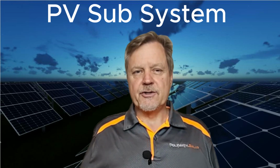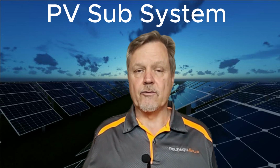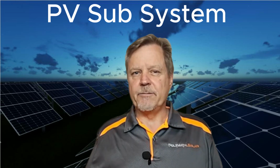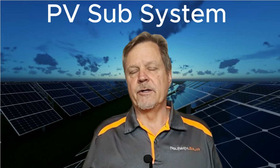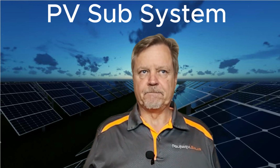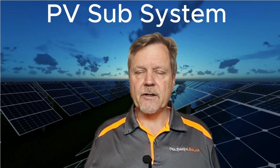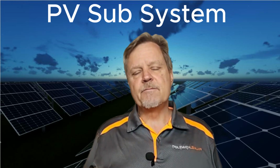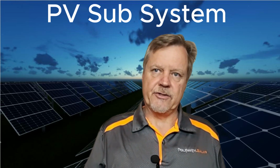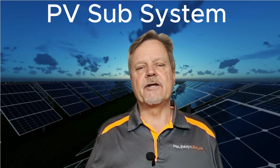If the PV generator is too big, well, that's a big thing. I'm going to spend a bit of time later to talk about the PV generator and the ratio between your load consumption, the battery size, and then the PV generator. There's a big, important relationship that many installers miss that you need to understand. In essence, if you have too many solar panels on the roof, then you harvest more energy than the house is using and what you need to recharge the battery. So if the battery is full and the house is not using the energy, where is that extra energy going?